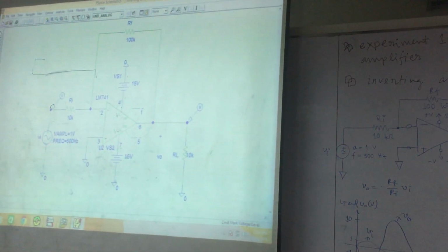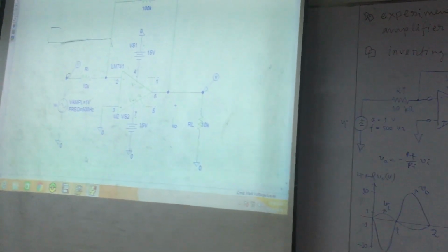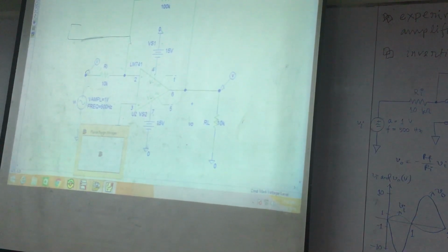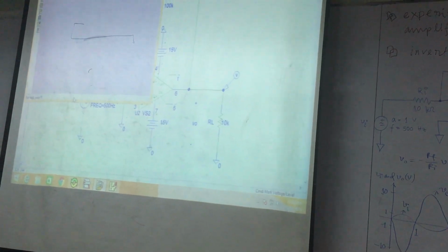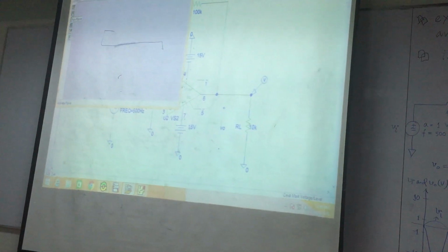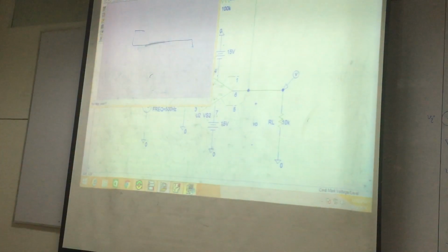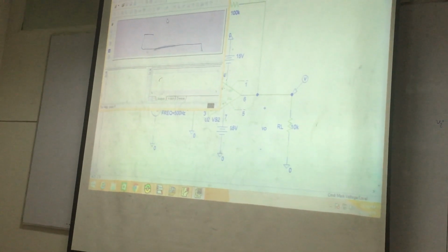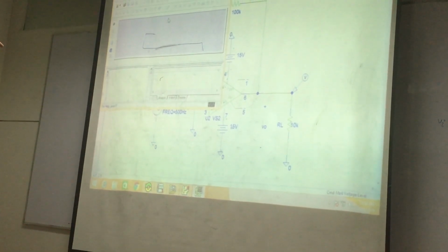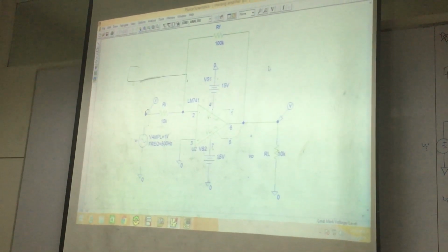Now how to simulate. So this is the process. You have seen the same process over and over again, 202, 204, 206, everywhere. So you should be able to figure it out. So, design manager. Number 2 option from top, run PSpice. Something is going to appear. This is that guy I'm talking about. Okay, so 3 windows you can see over here with nothing inside now. We'll use it later. Get back to the circuit here.